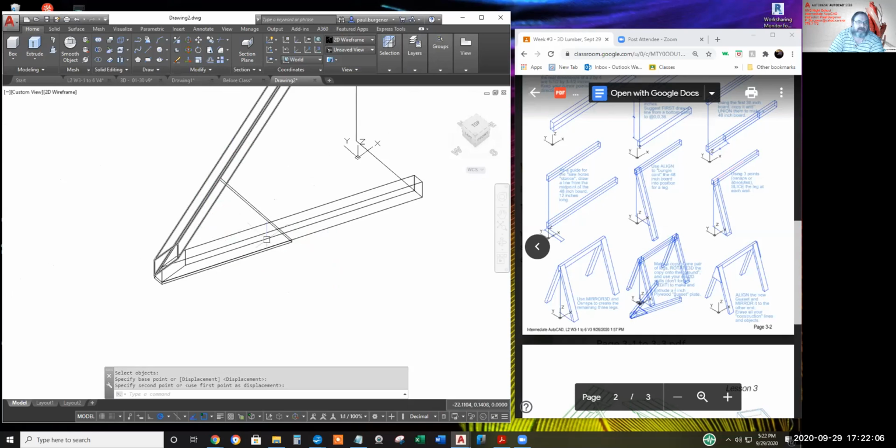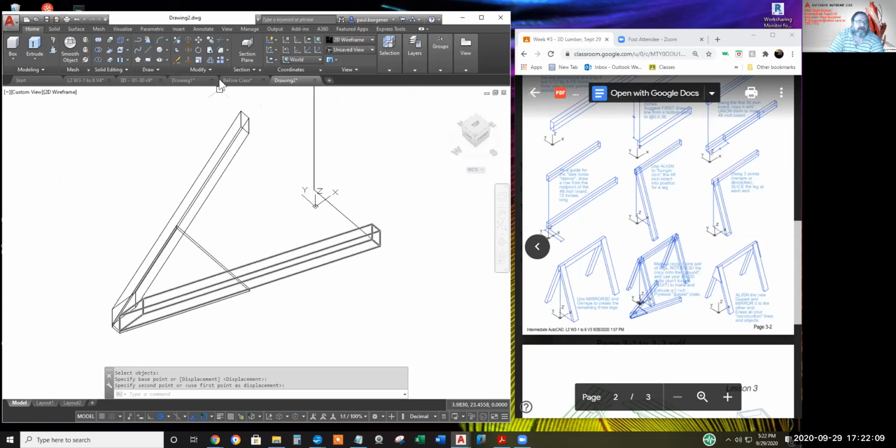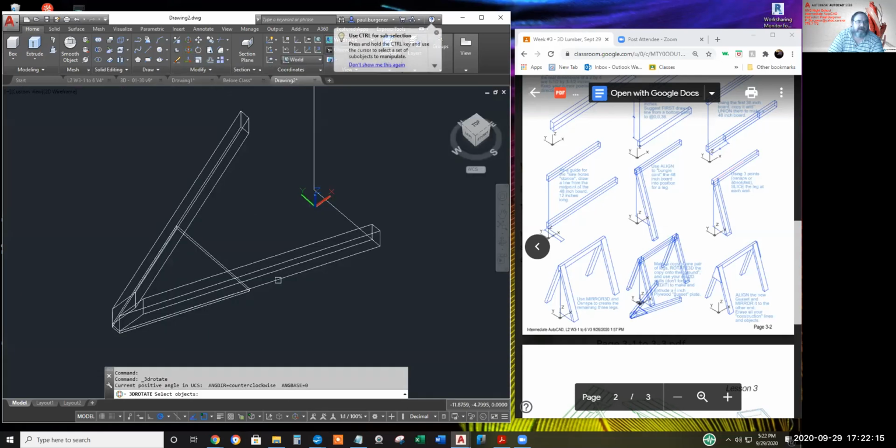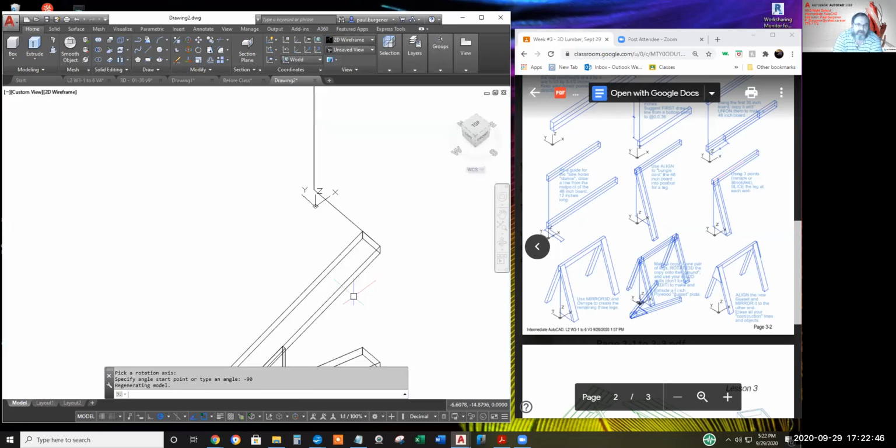Now we can upright this entire assembly. Let's use the 3D rotate command. Select everything, hit enter, specify where the hinge pin goes, specify the green circle of the 3 rings. I believe typing 90, -90 will send it back where it was. -90.